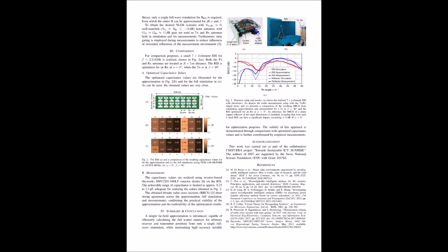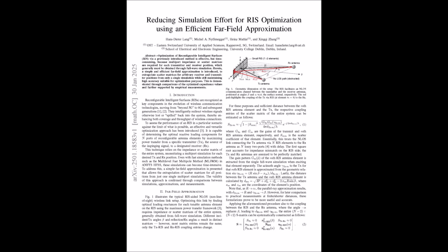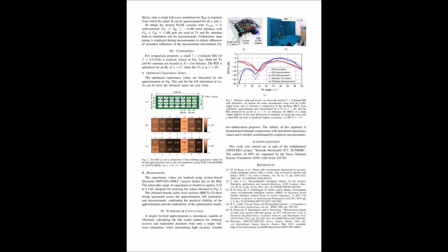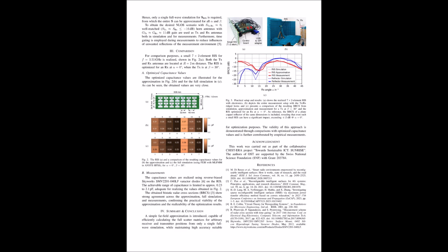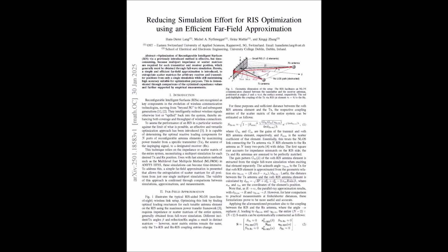What about that next part of the equation, the one with all the G's and D's? So that second square root term represents the free space path loss. Free space path loss, okay. It basically describes how much the signal weakens as it travels through the air, and it depends on a bunch of factors. Like distance. I'm guessing distance is a big one. Distance is definitely key, and that's where d_TX,m comes in. So d_TX,m is the distance between the transmitter, TX, and our mth RIS element, but we normalize it by the wavelength. So divide it by the wavelength of the signal. Precisely. And lambda is our symbol for the wavelength.